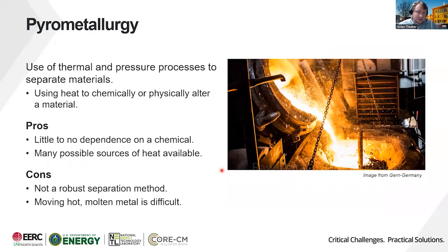Now, pyrometallurgy: the use of thermal and pressure processes, heat, to separate and chemically and physically alter these materials. And there are advantages to doing that. First, there's little to no dependence on any chemical, which is good. There are many possible sources of heat or process gases, be it electric heat, coal heat, natural gas heat, hydrogen heat, indirect heat from steam, many different cases. And so there's a lot of power behind pyrometallurgy.